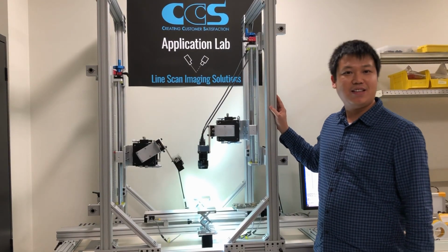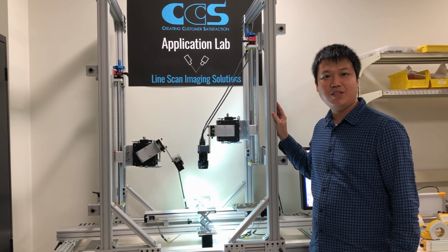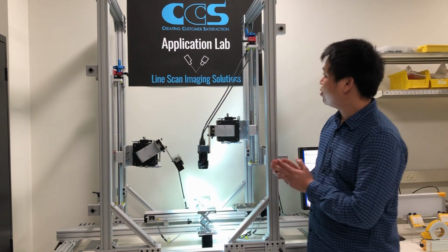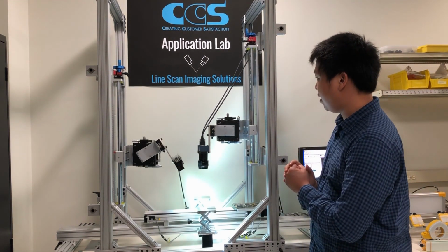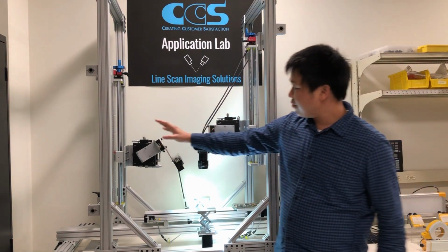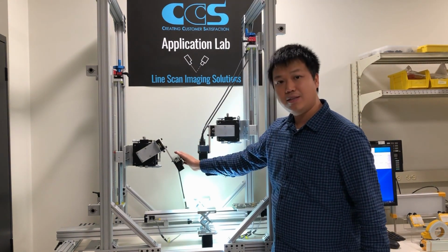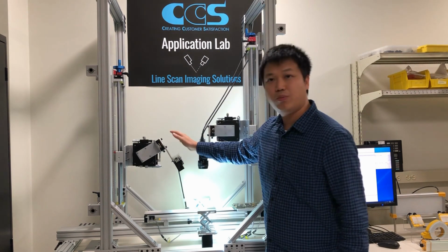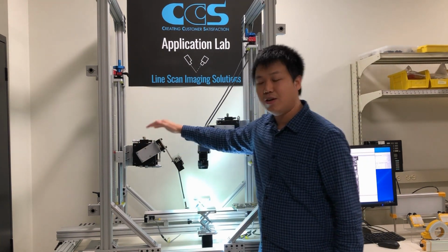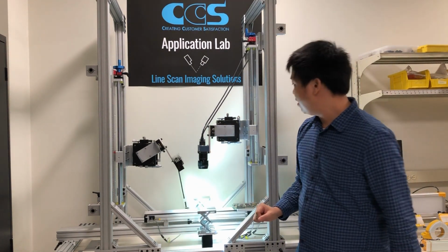This is the line scan testing station we just talked about. When we designed it, the basic concept was to make it flexible. We want to make sure this station can handle most of the major line scan applications. On the left side is the lighting. We can swap out different lights and change the angle for bright field and dark field. It's also really flexible for different working distances. We can also put the light underneath to get the backlight result.